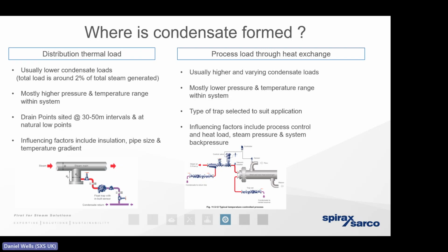And it's good working practice to apply the same rule of thumb for the process as well. Because if you think of a heat exchanger as a huge lump of metal, it essentially means that if we've got a process that's stopping and starting periodically, it means when that process is starting up, when the steam is energizing the heat exchanger, whilst the heat exchanger is cold, more and more of the steam is going to be lost to the atmosphere and to the heat exchanger itself before it enters the process.